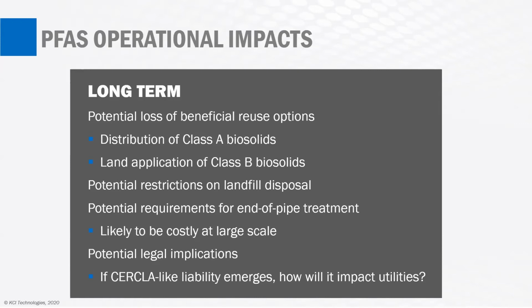We have a question that came in. The question is, what are safe ways to dispose of biosolids? If the question is related to biosolids in general, any of these routes that I mentioned here, our Class A distribution, land application, and so forth, those are all good, safe ways of getting rid of biosolids conventionally. If the question is related to how do we get rid of biosolids with PFAS in them, I'm actually going to defer that for just a few more slides, because we're going to start talking about treatment, and I've got a whole section talking about how do we treat biosolids with PFAS in it. Does that answer the question? I believe so for now. Thank you. Okay, very good.